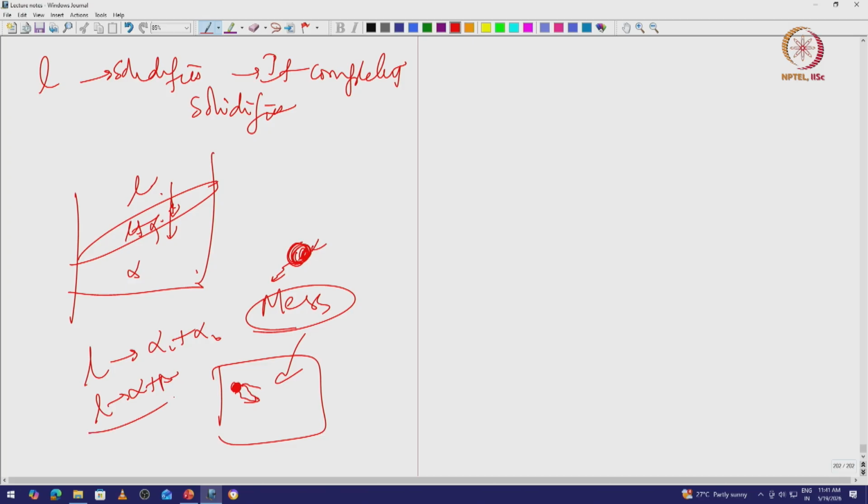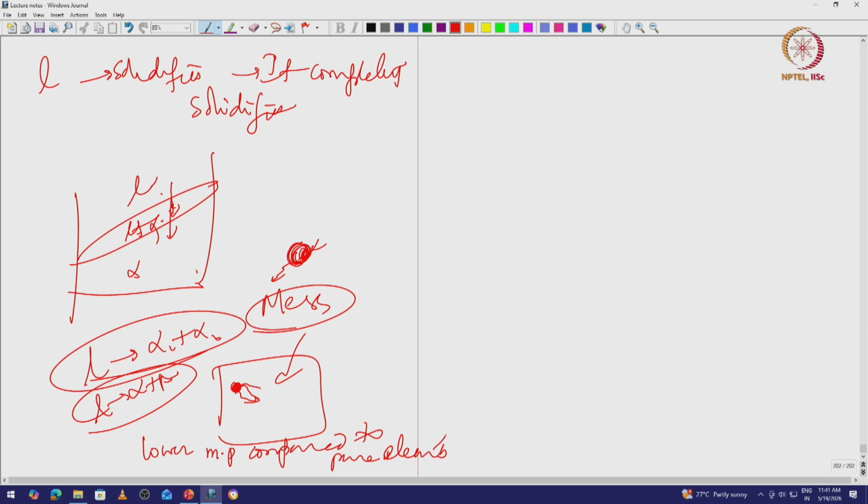So, it is hence safe to use eutectics, and also the added advantage of eutectics is I have a lower melting point compared to pure metals or pure elements. So, I can do this processing at a lower temperature, and once it cools below Tm the liquid just becomes alpha plus beta, or lead plus tin or something like that.